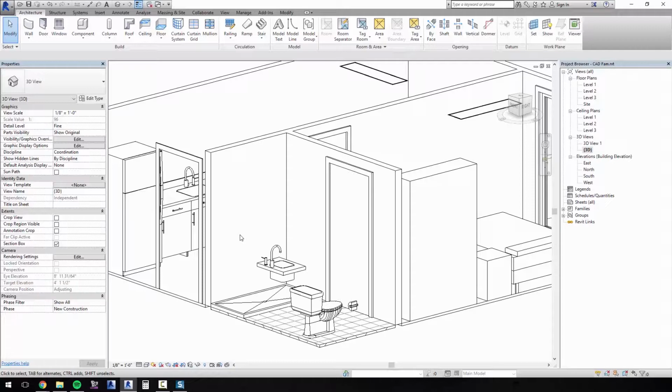And I cannot stress enough to never, ever bring a CAD file straight into your Revit project unless you absolutely have to. But if you're bringing in specific furniture or objects for your project, do not bring them straight into your Revit project. The best option is to create a family first and then bring that family into your project.